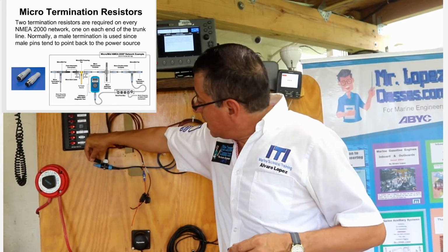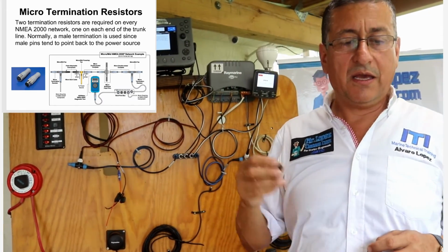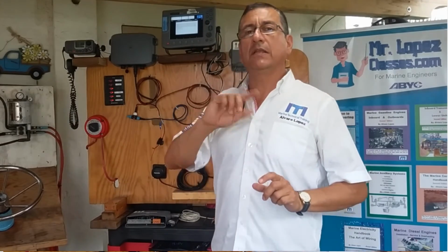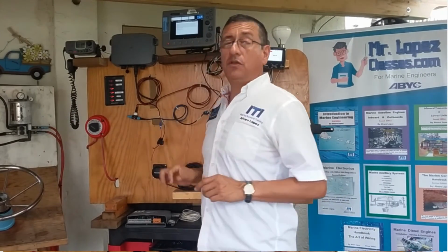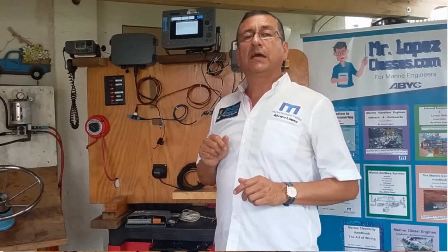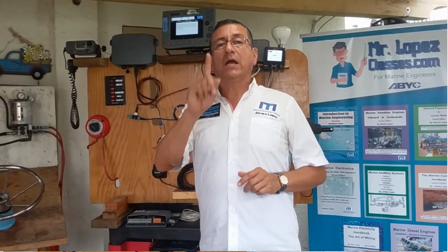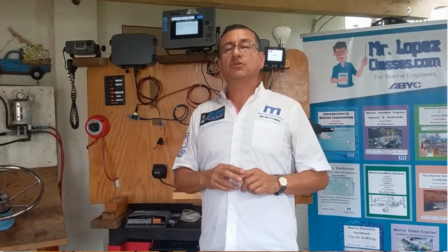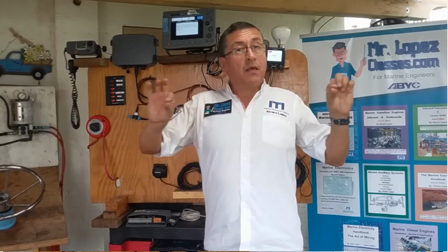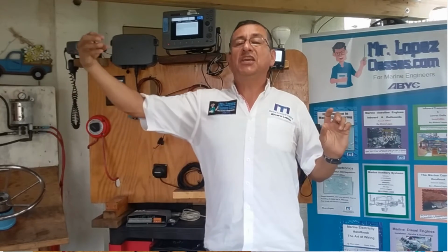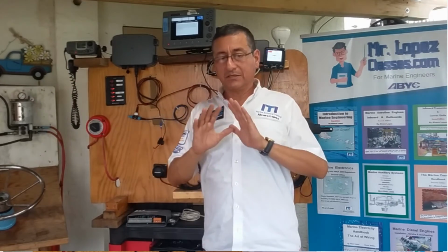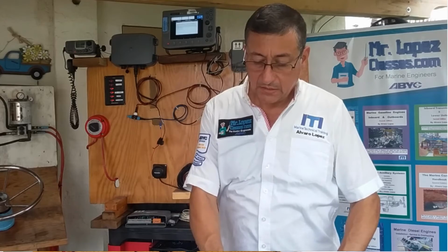If you don't have a terminal resistor installed at one of the ends, the signal is not traveling, and immediately you have a code on the computer indicating that one additional terminal resistor is necessary. In other words, the backbone is a linear element, and each end should be finished with one terminal resistor. That's critical. This is mandatory.